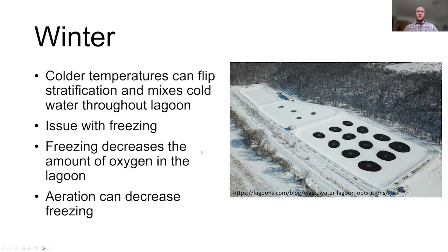So if there's freezing on the top of your lake, there's not going to be a lot of oxygen exchange throughout your lagoon, of course, because you have that layer of ice. So something that can help with this is aeration. In this picture on the right, you can see they have all these air diffusers in there, and they're creating places where it's melted, where there's no ice. So there can still be some oxygen happening in there.